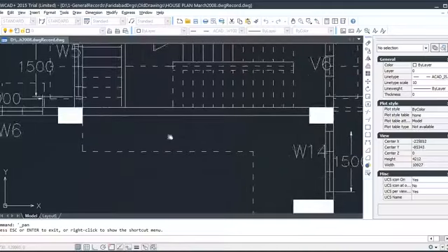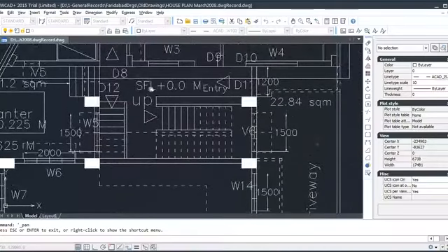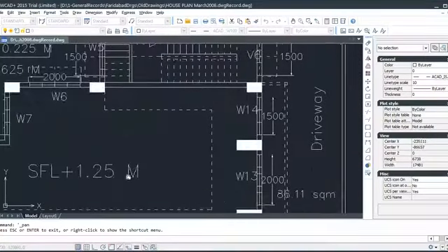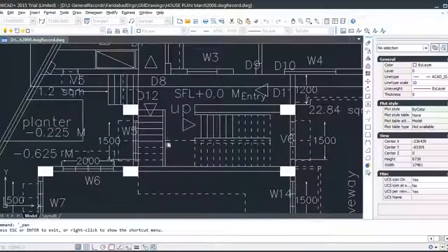This is the difference: here there is no basement area, and this one is the basement area, the hall area. So there's a difference of, you can say, 2.5 feet or 45. We have provided some steps here to come up here. As you can see, we have used a 5 inch or 125 mm riser. The vertical portion of steps is called the riser, and the horizontal portion is called the tread, T-R-E-A-D.